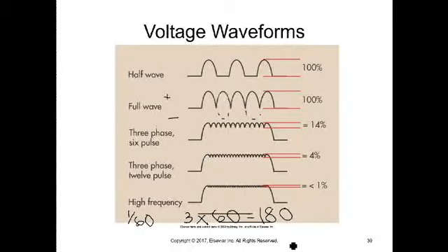And then that's on the positive side. But when it's fully rectified, you have to include the negative side. So you're going to do that 180, because it's fully rectified, times 2, which equals your 360 pulses per second. And I hate that it does that line, but anyway.